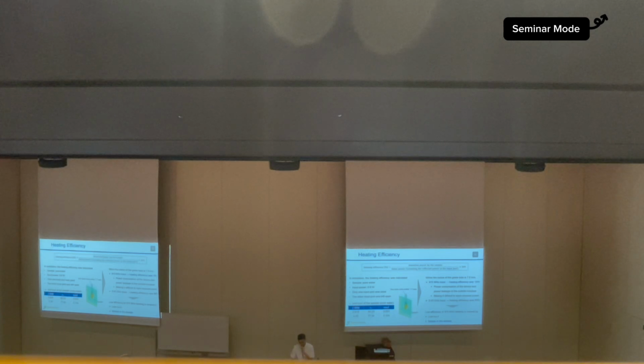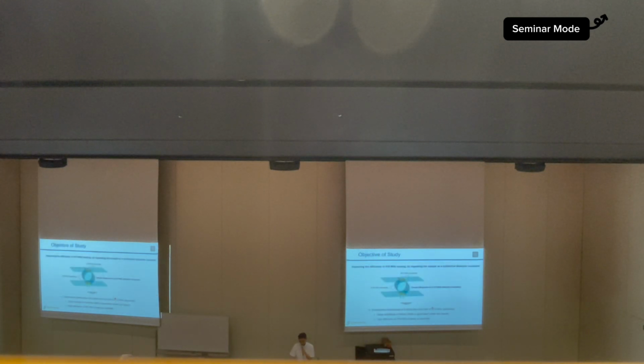But not only loss tangent, also modes of electromagnetic wave in the sample are related to the heating efficiency. So today's objective of study is improving the efficiency in 915 MHz heating by regarding the sample as a cylindrical dielectric resonator.